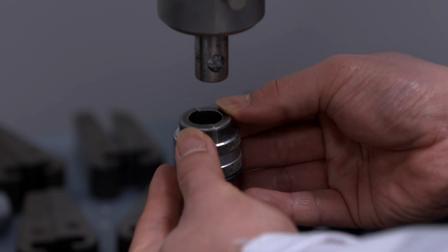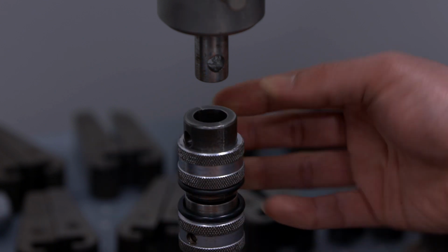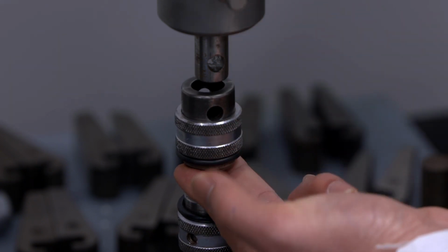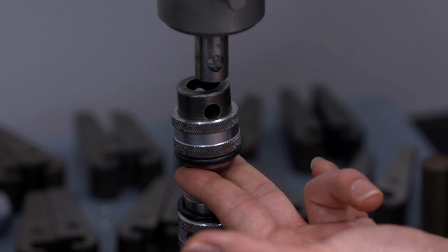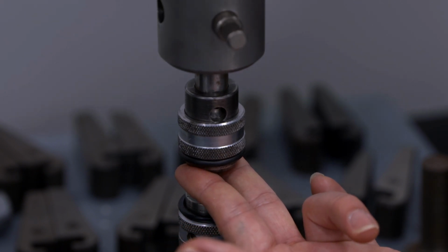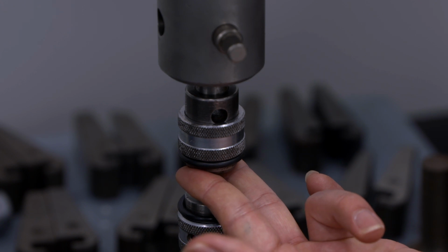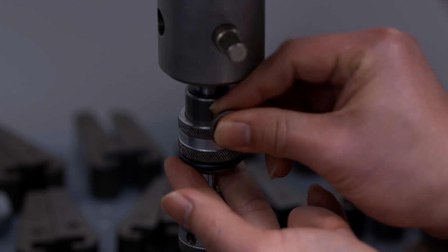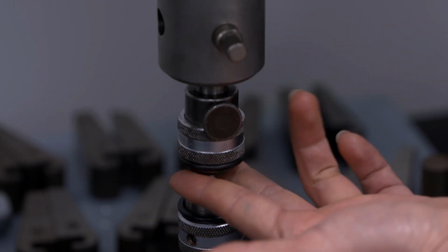You need to hold the whole grips and specimen like this, and then use the panel to slowly move down the crosshead. Then another pin to locate the upper grips.